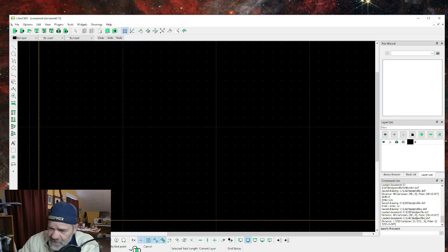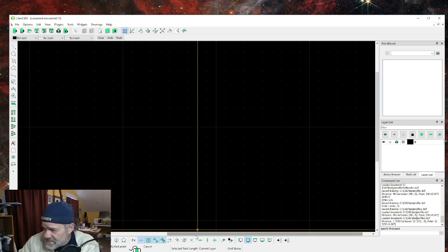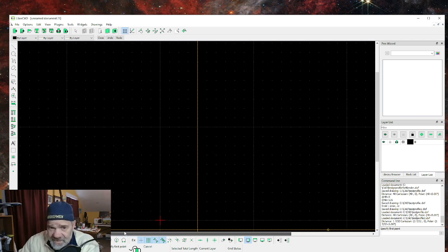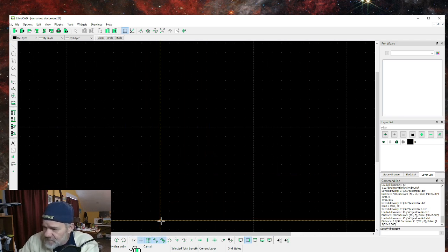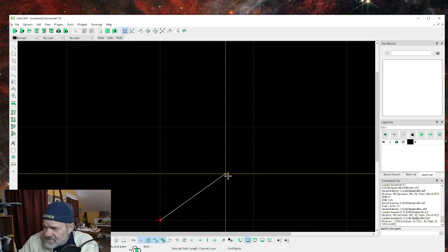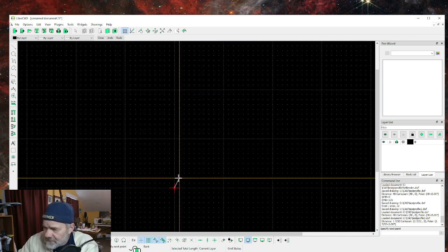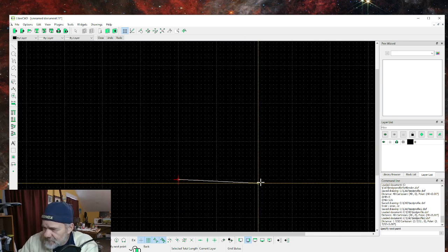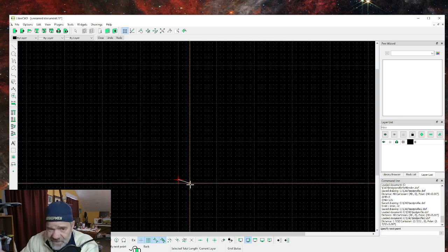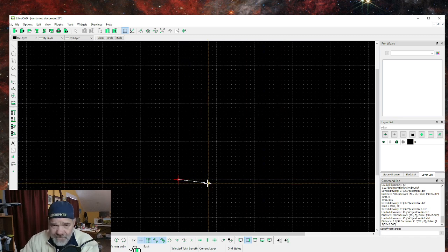I'm going to do a 2-point line. I'm going to start here. Of course, you guys can't see where I am, so I'm going to slide that over here. All right, so I'm going to click here, and let's say I want to make a 10-foot line straight to the right. From the point I clicked, I hit the @ symbol.